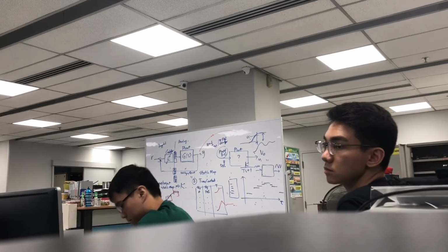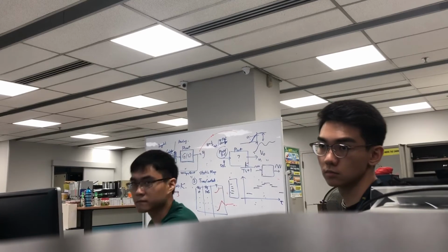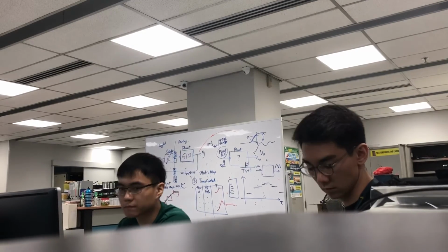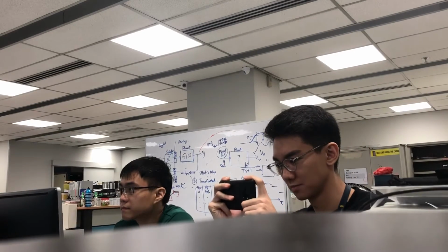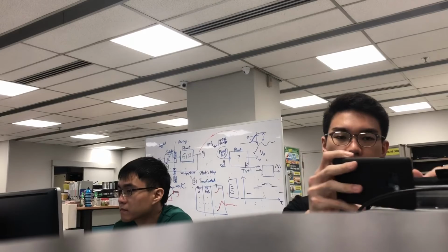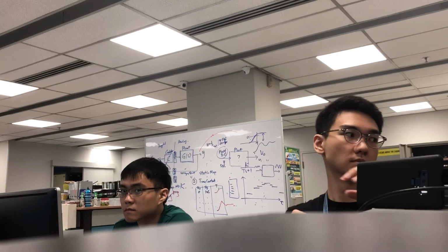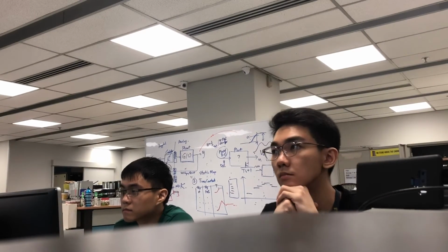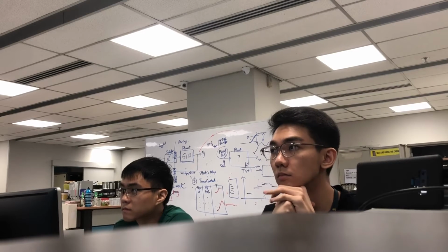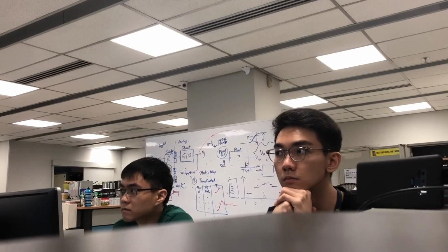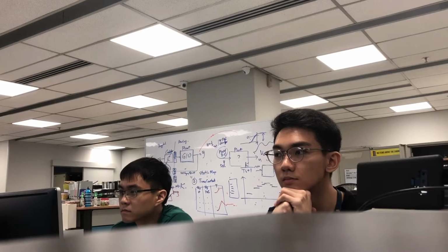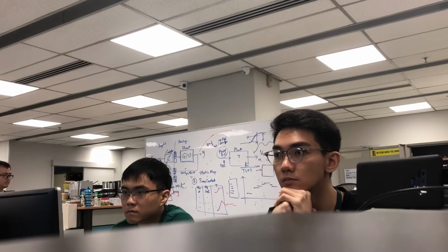So before you go away, let me remind you one more thing. I think that's very important. Okay, so here, just now I already said this. When you don't see the expected output, you don't see the PWM signal, ask yourself this question: which type are you using? Are you looking at the right pin? Okay, all right.